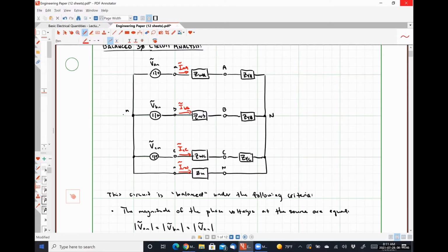In a real three-phase system, everything is based off of what we would call a floating potential, meaning that there is no direct connection to ground. But to make our math simpler here, we're just going to assume that that source side neutral is at a potential of 0 volts. Purely mathematically, everything will be measured with respect to that.